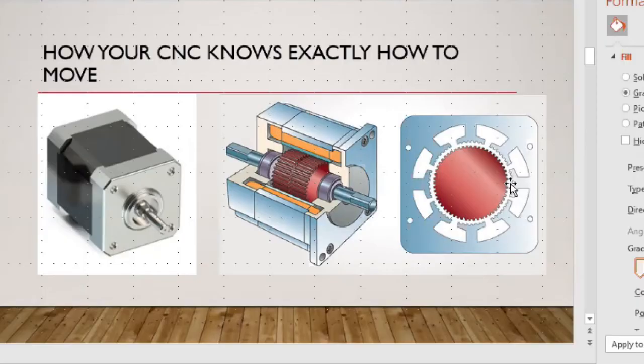You'll see that your stepper motors, if you put together something like a Bob CNC, have 4 wires to them. And those wires are tied into these coils consecutively. So 2 wires would be tied into the up and down coil. The other 2 would be tied into the next coil. The first 2 would be tied into this coil, and so on.